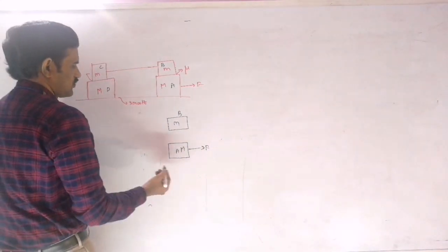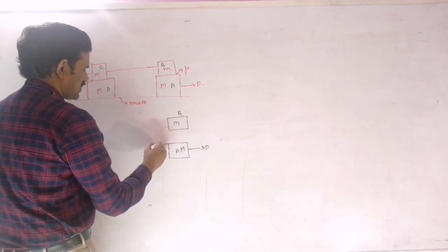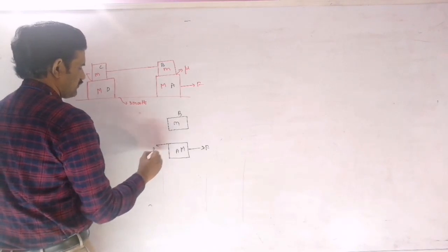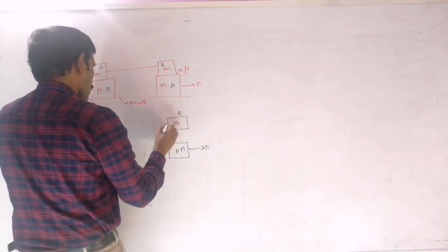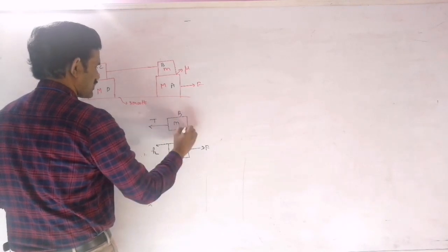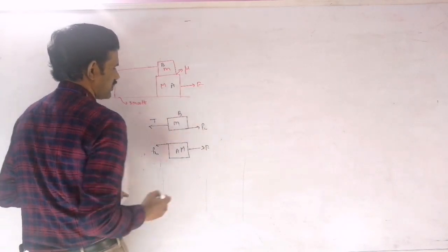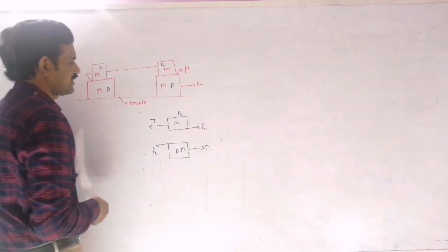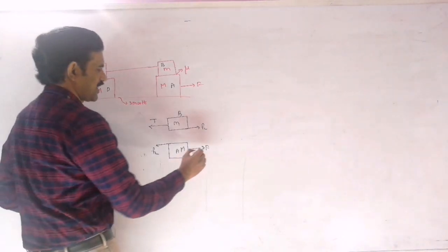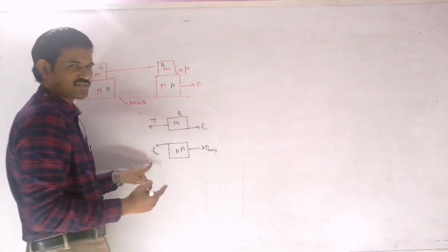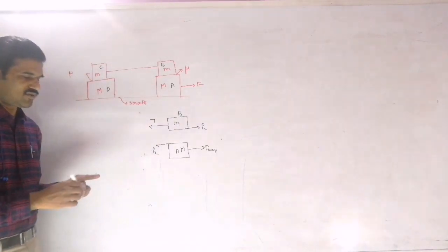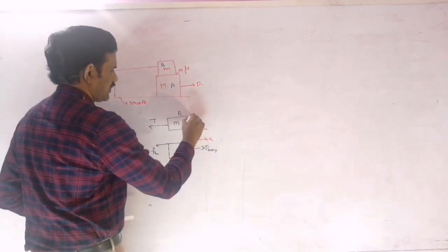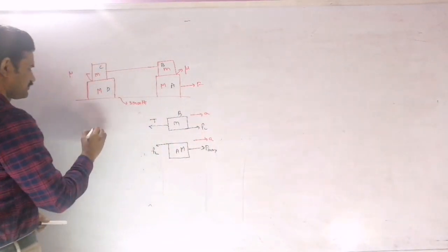Right? And we are taking the maximum force there, so here I am taking F limiting, the limiting friction. Now on this block some tension will be there along this direction, and F limiting will be there along this direction, right? So this will be the situation for A and B. These two blocks we are calculating here. As we are calculating the maximum force, I am taking the maximum limiting friction there. They are moving with the common acceleration here. So that is the assumption we are taking here. Its acceleration is A, and this acceleration is also A.